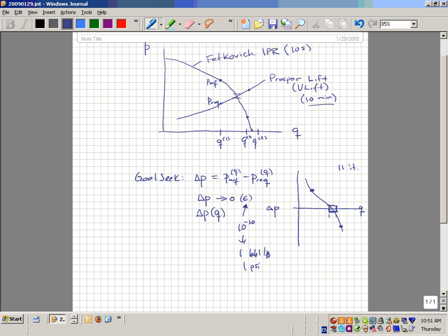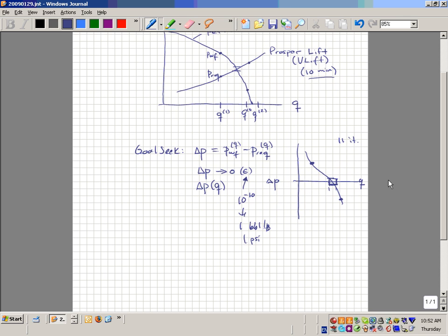If the function becomes very parallel to the axis before it crosses, over the range of Q, if this becomes very flat, something like that. That's what the Rachford-Rice function looks like, and that's why sometimes it's hard. Because then if your tolerance is as I've drawn it here to here, then we might get an answer there, and we might get an answer there. That would be within the tolerance of delta P. Now, why might that cause a problem?